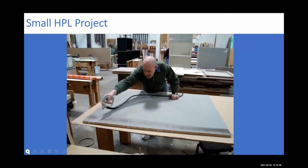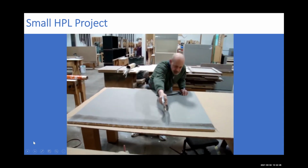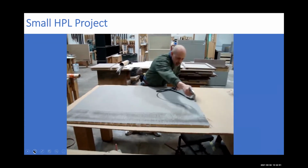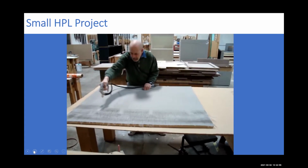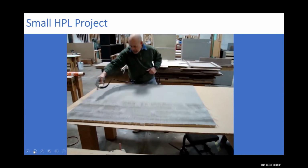In a smaller shop, it's more likely that the mill worker is using contact adhesive. This is the spray application of contact adhesive. It's important that the applicator overspray the edges of the sheet as well as the substrate on both sides so that the laminate adheres properly. You can see he's putting a good amount on there, very even, very consistent, and he's going to put this on, again, both sheets of laminate and both sides of that substrate.